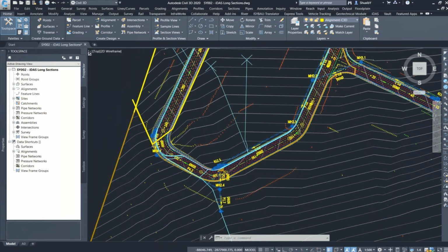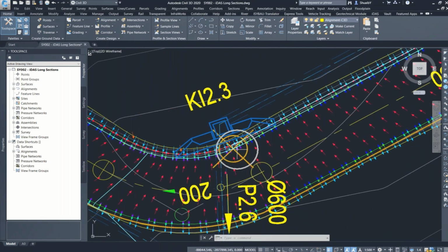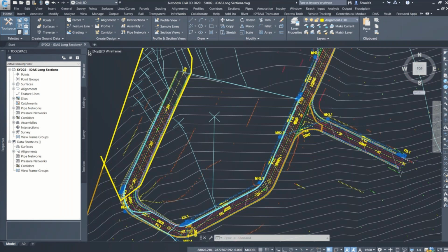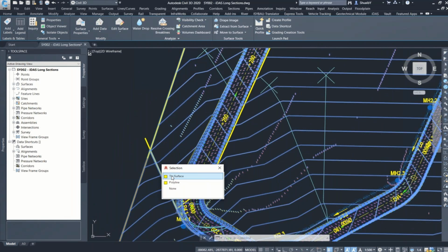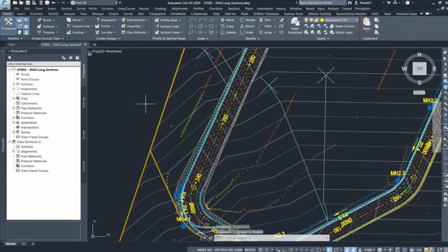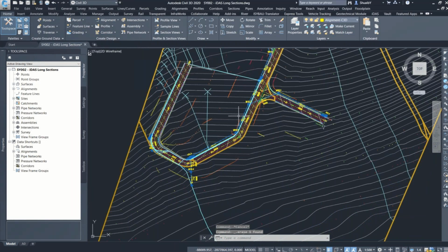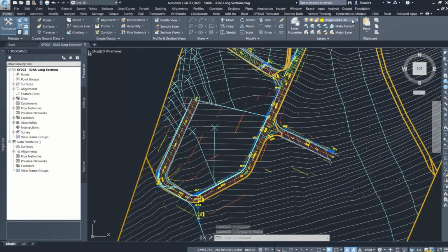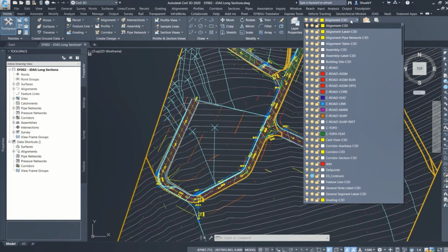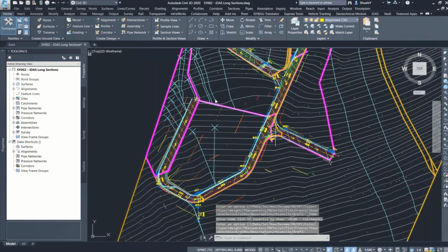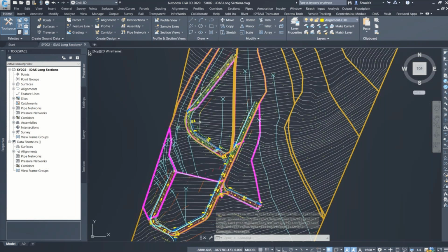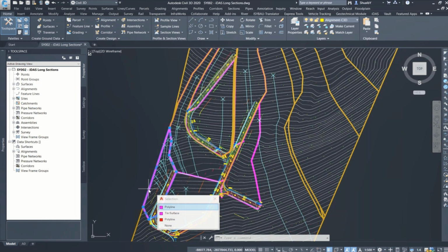Right, so I've got other curb inlets at different locations where the water would probably gravitate. Okay, and what we're going to do, just to save time, is I've already drawn them. So I'm going to select this and delete it. You understand the methodology. Again, all my webinars are based on understanding rather than what you're seeing on the screen. I want you to understand what I'm doing, right? So I'm going to unfreeze this layer. I've already bolded it for you. And here we are. The magenta lines actually represent the catchment.